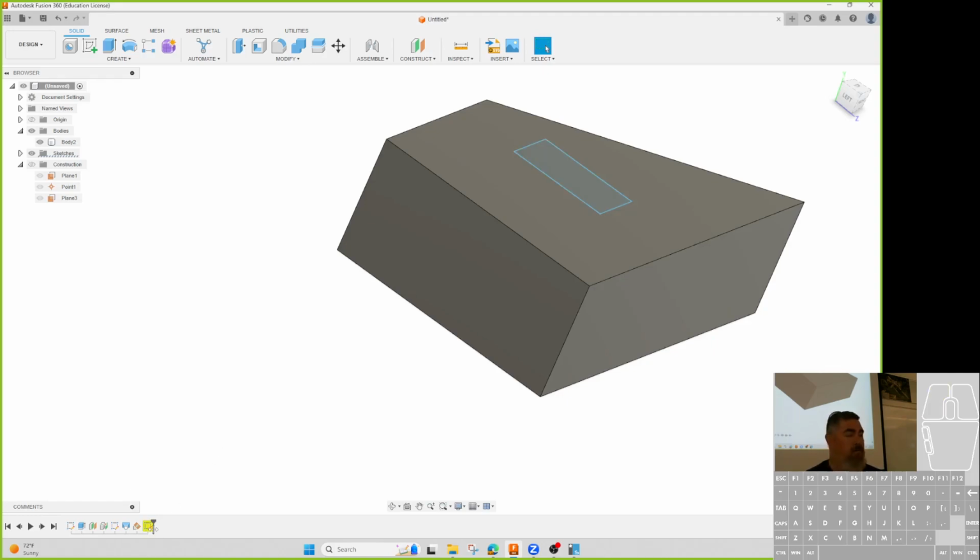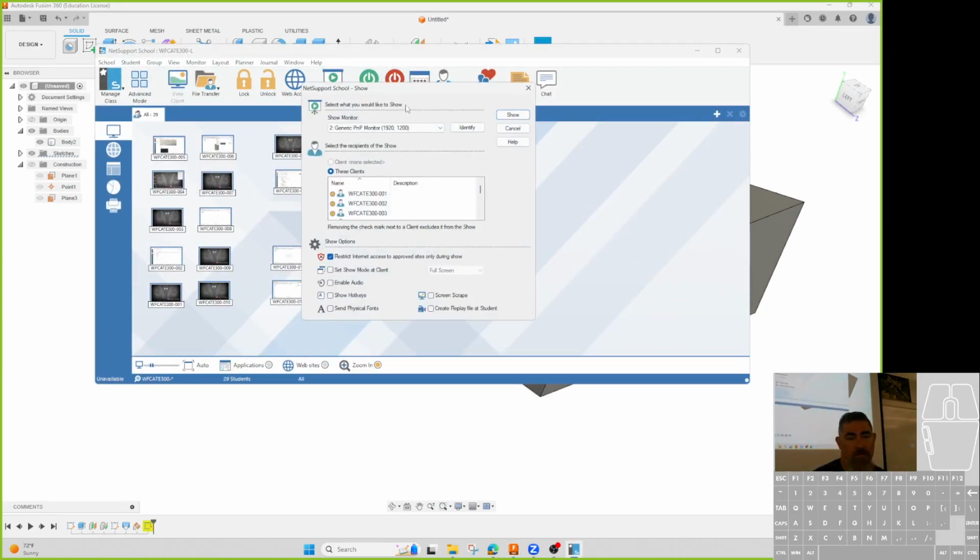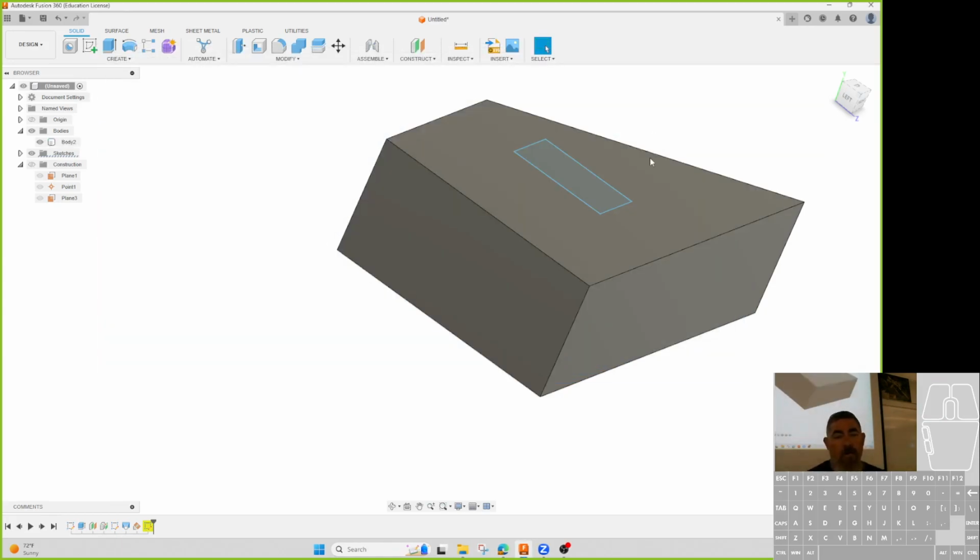See, it's yellow down on the timeline. Oh, and I'm not showing it to you guys. There, sorry. See down here, the timeline, it's yellow now. That means it's broken. And if I ask it what's wrong, the sketch plane is lost. The top of the part's still there. What happened? I created a sketch on an old sketch.